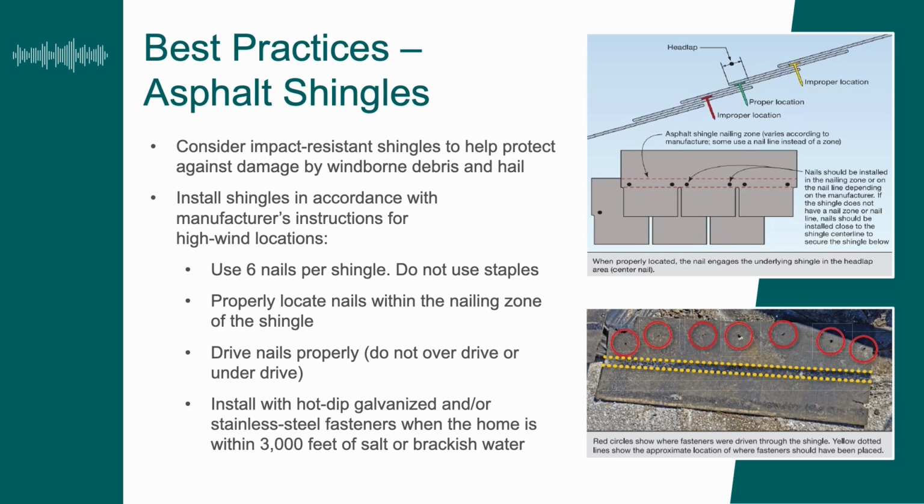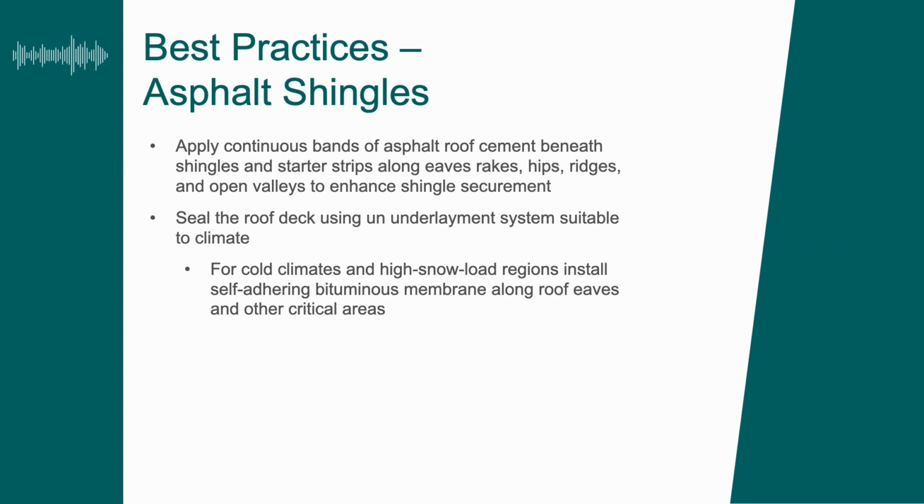In coastal regions, you have to be careful with your fasteners. You're using hot dip galvanized or stainless steel fasteners when the building is located close to coastal areas with salt water. And driving nails properly. That applies to all these roof covering systems. Do not underdrive, overdrive fasteners, or fasten at an angle. For asphalt shingles, also applying bands of asphalt roof cement in critical areas, such as in the eaves, enhances the shingle securement.